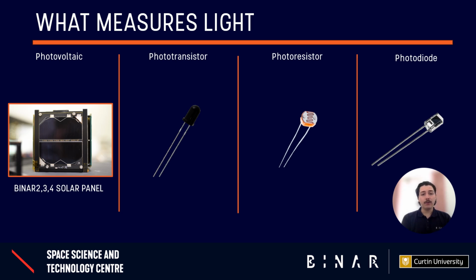determine the general direction the sun is, but due to this large bandwidth and the FOV, we can find a more applicable sensor. On the other hand, phototransistors let current flow through the legs when light is applied to the sensor. These are great sensors as they can push large amounts of current when there is light, which is good in high power applications. For us, we want more of a passive sensor, the lowest amount of power being used so that we can run our sensor as long as possible.